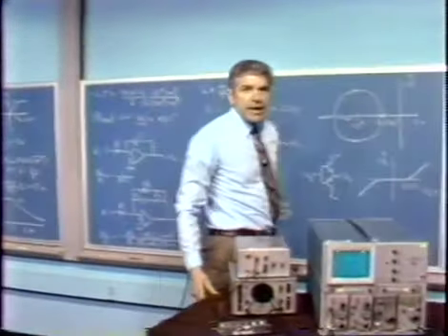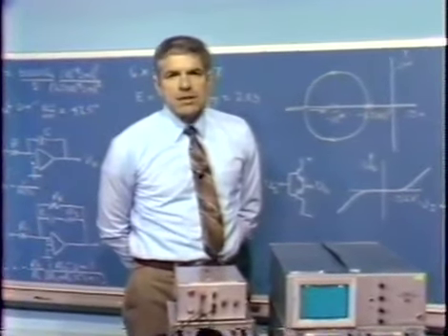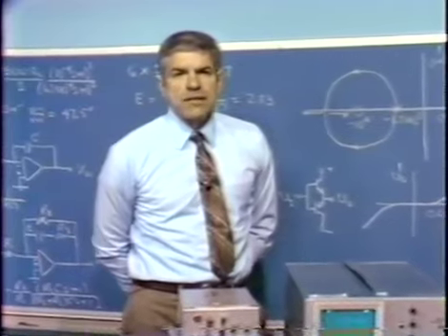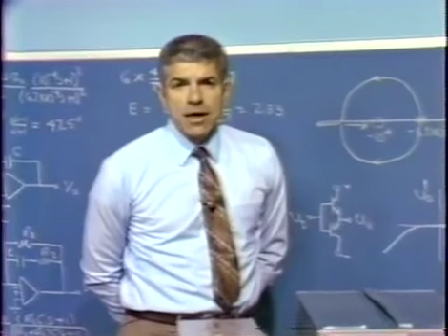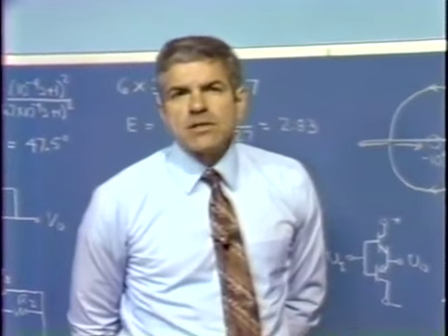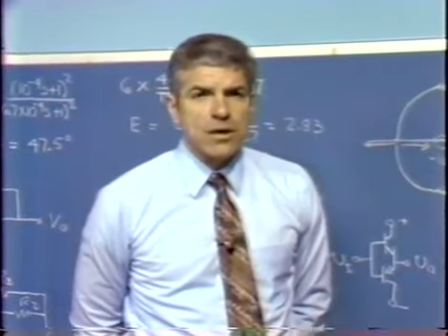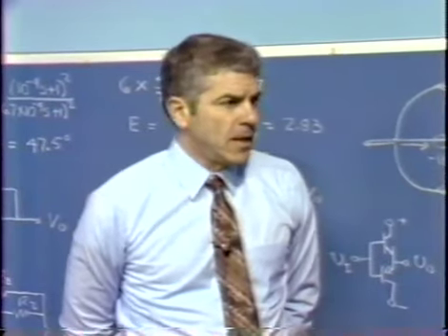What we do, and there's certainly no generality in nonlinear compensation, is look for a point in the loop where signal levels change rather dramatically when the system starts to oscillate, and see if we can somehow use that information to improve the performance. We found a rather easy way to do it in this particular case.